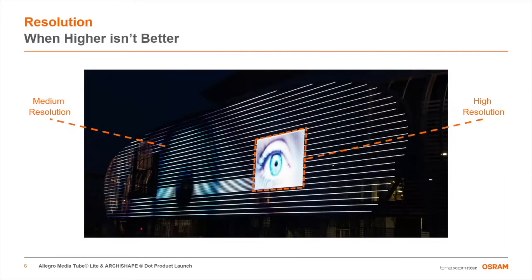This is the Grand Stade in Metropolitan in Lille. On the right, you see a traditional LED screen with this high resolution eyeball, probably a pixel pitch, side to side, butted end to end, of about half an inch. Meanwhile, the entire facade is turned into a media light screen on a grid, per se, of continuous tubes left to right, spaced about 20 inches top to bottom. So you have a pixel pitch of 1 inch by 20 inches.